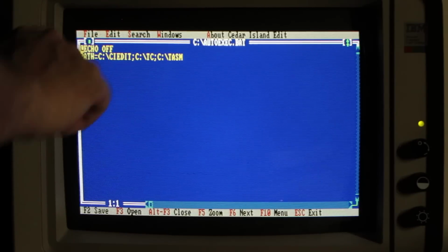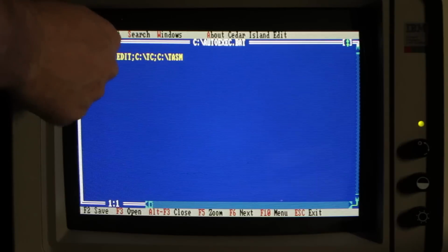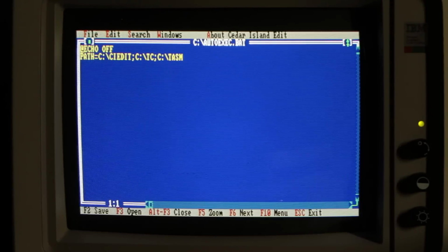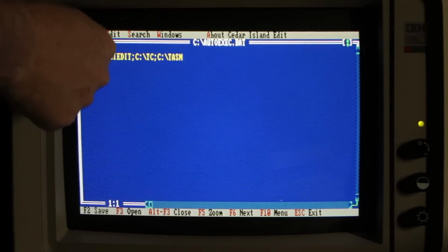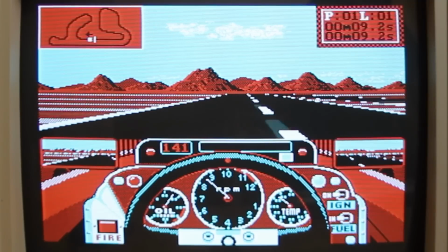The ASCII code is used to look up in video ROM which pixel information should be displayed, and it figures out which scan line of that character it should be displaying using the row address, which will be 0 to 7 on CGA text modes. So that's how the text modes work. How do the graphics modes work?